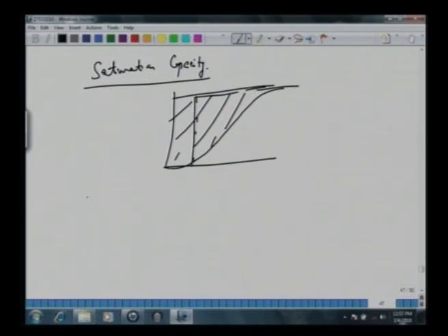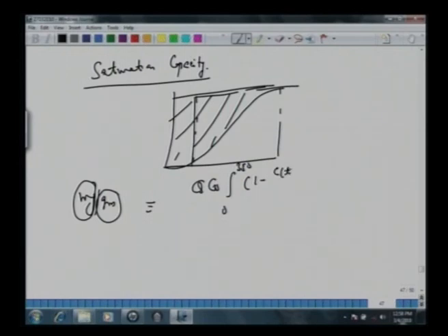So saturation capacity is nothing but milligram per gram: how much milligram of adsorbent VOC has been adsorbed per amount of this adsorbent. So how much it has been adsorbed, you have to integrate Q equals C0, 0 to 350 minutes, that's your saturation time, of 1 minus Ct over C0 into dt.